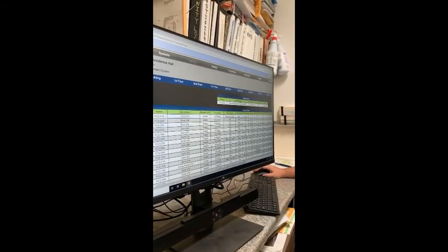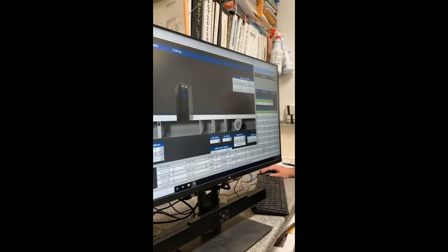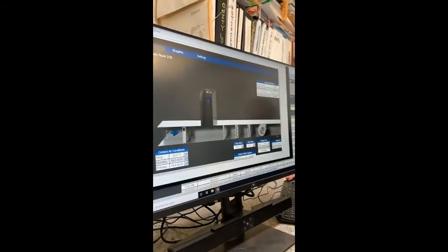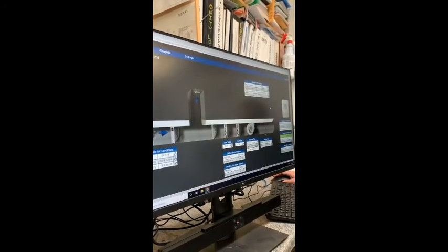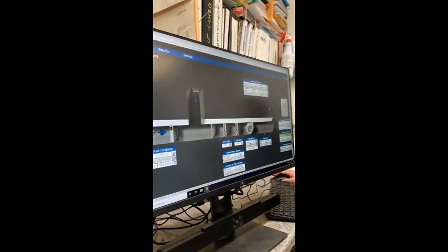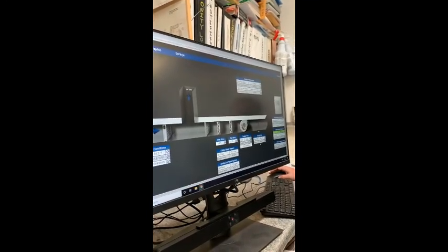I'm just wondering if we'd be able to tell if a motor's not working. So we do have fan status. They have temperature. They don't have pressure, I don't think. Normally when things are zoomed in, you wouldn't have to scroll. But we have the fan status. You can see what the fan command is, the valve commands, and the supply air temperature.